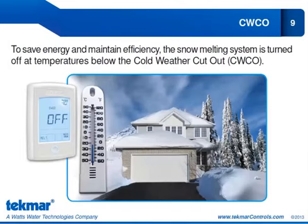Likewise, the 654 features cold weather cutout. So when we are at very cold temperatures, it is very inefficient to operate our snow melt system. We will not be able to get that slab surface up to temperature, certainly not efficiently. So when we see those very cold temperatures, like what we've shown here at minus 10 degrees Fahrenheit, then we're not going to operate our snow melt system.